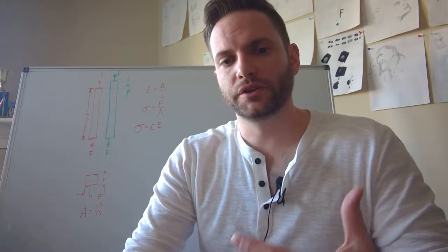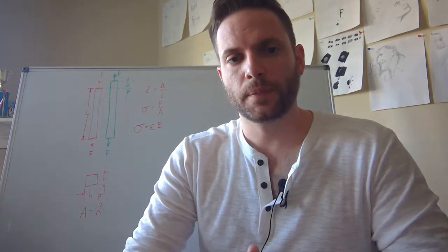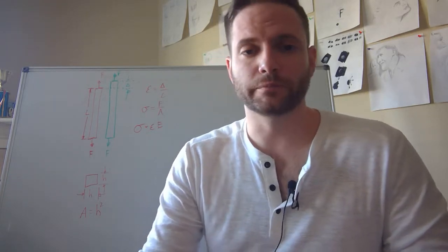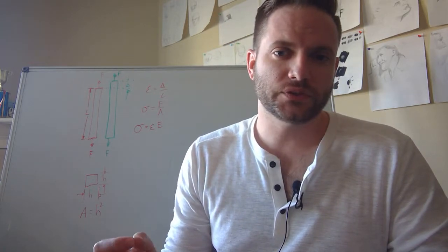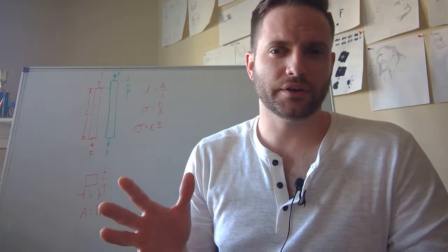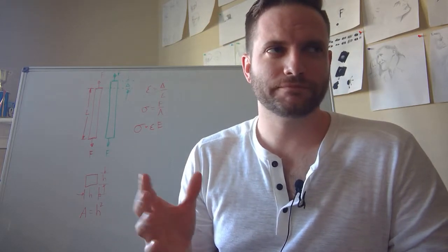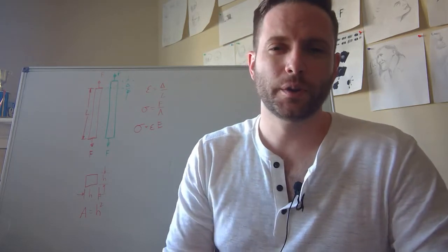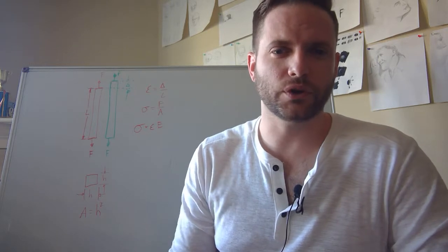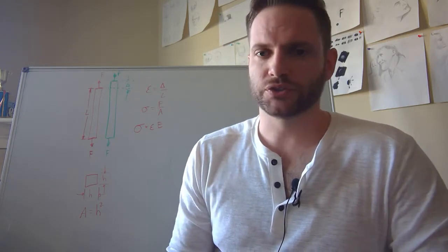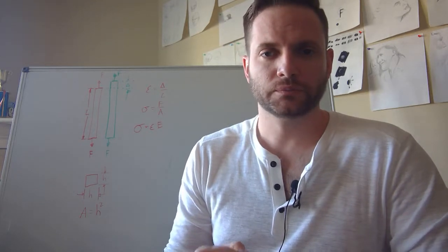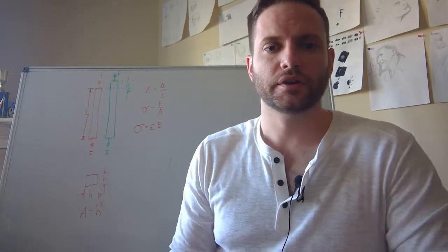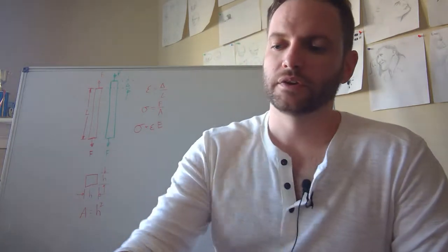Now this is a linear relationship. It's simplified. It's very useful though. Most of the time when you're dealing with engineering, especially when it comes to metals, the strains that you see in real life are usually less than 1%. Metal usually has some ductility, so it can stretch up to maybe 10% or so depending on the alloy. But usually you design to some really low strain level. It's just, metal doesn't move a lot. It's very stiff, and you typically see these low strains where all these crazy other phenomena that can happen at high strain don't matter.